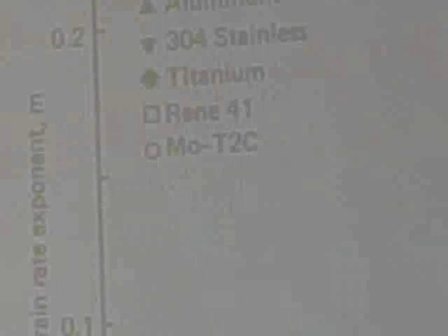IN 100 is a nickel-based superalloy, 738, 629. This one actually is a copper base. IN just means International Nickel. And then nickel aluminum bronze, which is basically a copper base alloy. So you got copper, aluminum, iron base, and of course we have titanium base as well, superplastic alloys. But in general, they're going to be things that occur at about 30% one phase and another phase. It can be 30% plus or minus 10 or 15%, but it's going to be in that range. Because you have to stabilize the small grain size and not have it just take off on you.